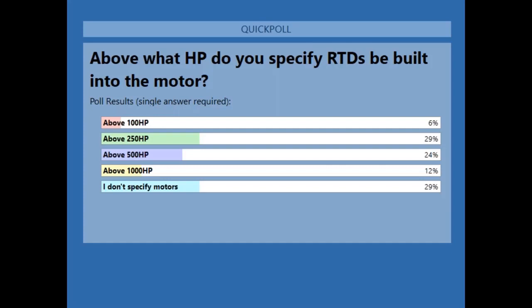So typically what we see, because we have 12 RTDs available, we have 6 in the stator, 2 on the motor bearings, 2 on the pump bearings. Then we have 1 on a pump case if you've got a pump case. And the last one we use for ambient. One thing is we can use on both 369, 469, and 869, that ambient can be used in the thermal model. It's not part of the RTD biasing, but it is used in the model.